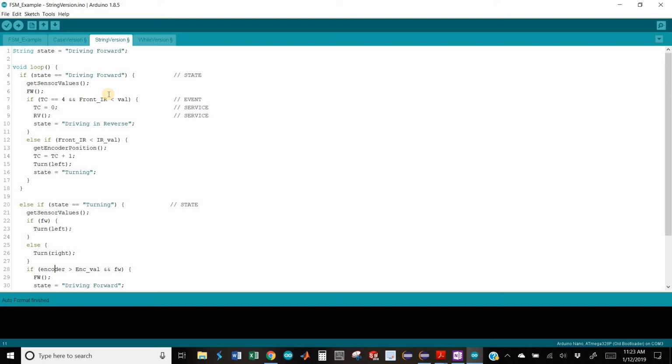so that they can know whether it's actually performing correctly or not, or whether they want to stop it in the middle of some operation. So you can have this state printed on your HMI. And it'll say it's pressurizing the system, it's bleeding it off, it's doing whatever. And they can determine, oh, hey, I don't want to stop the machine and shut it down yet because it's still pressurizing. So let's wait till it's depressurized before we pull the plug on it or something.